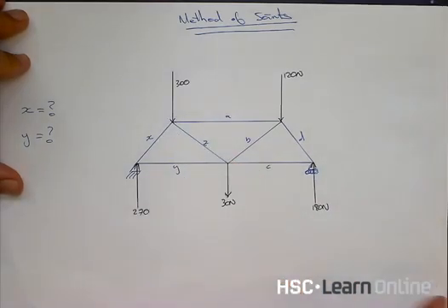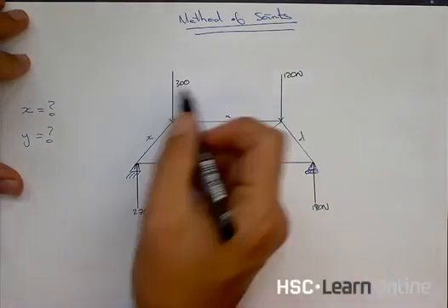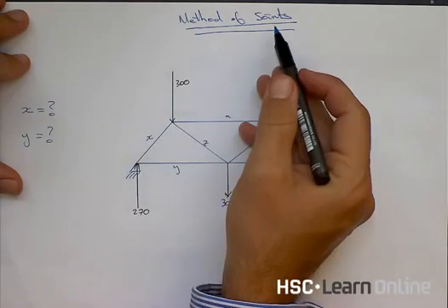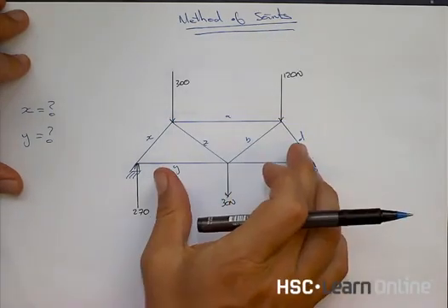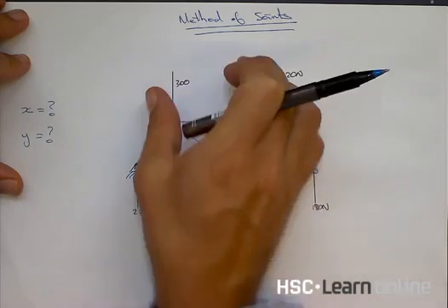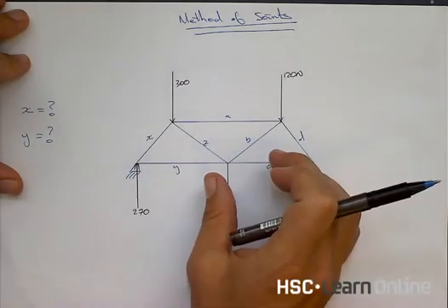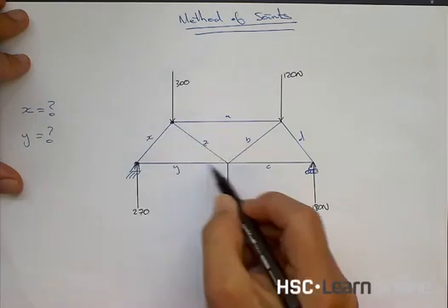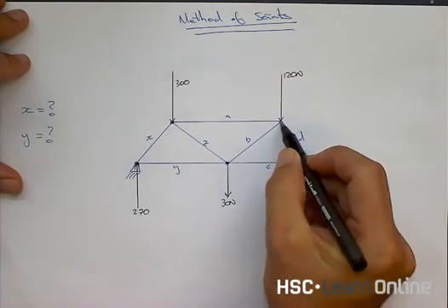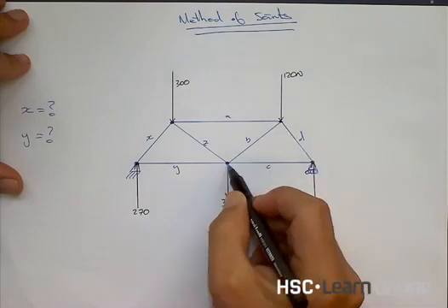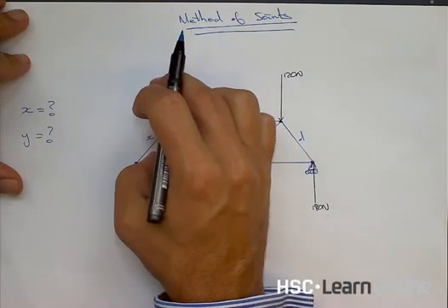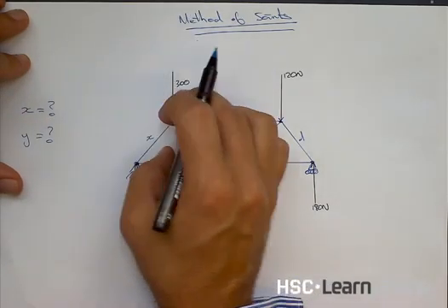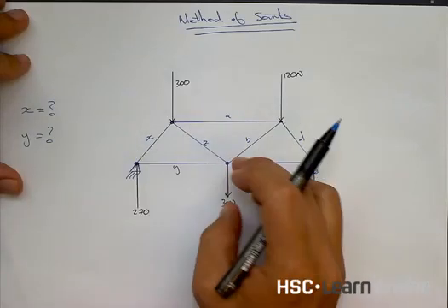And so we could do quite a complex calculation over here using all these different forces, but the method of joints says that if this bridge is not spinning or moving up or down and is therefore in equilibrium, each joint in the bridge is also not spinning, moving up or down. So each one of these joints we could choose and isolate, and say it's not spinning, it's not moving up or down or left or right. And so each joint is in equilibrium as well.